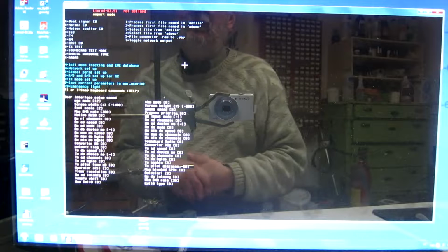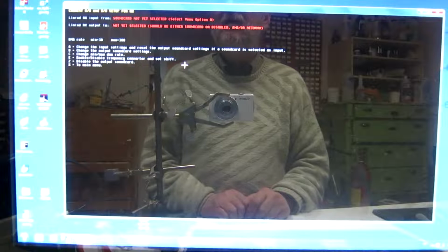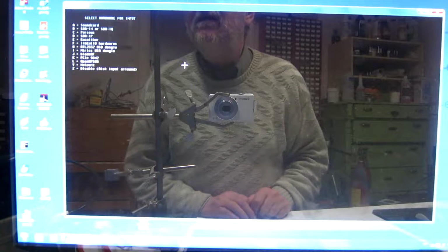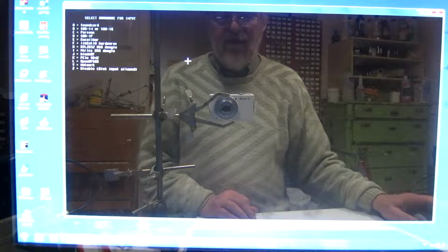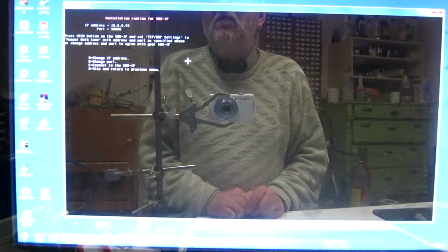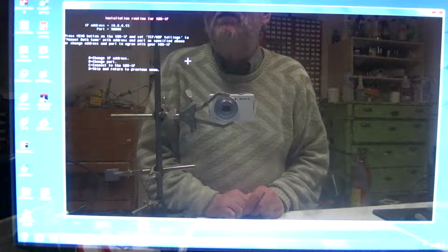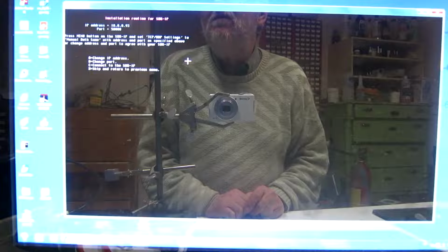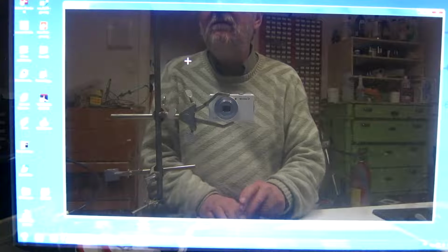Now go to the input and output setup, that is U, and then A to select something for the input, and here it is SDR-IP, that's D. And for some reason the default is the address that I have myself. So I don't change the IP address, I don't change the port, I just connect to the SDR-IP with C.